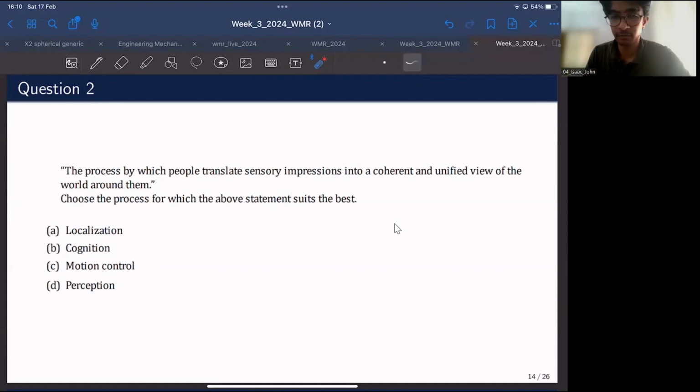For the upcoming weeks 4 and 5, we will progress from perception, from what we have collected from the sensors. We will utilize it for localization, to establish where the robot is on a given map. And cognition, in the sense that once it has localized, or has a full grasp of its current position, then it needs to know where to go. And it should also have a clear sense of how to reach that goal position. So that is where the cognition step comes in.